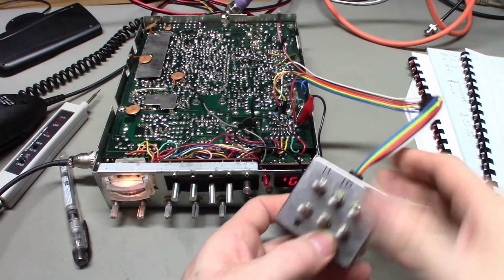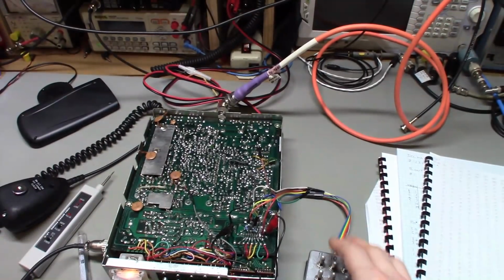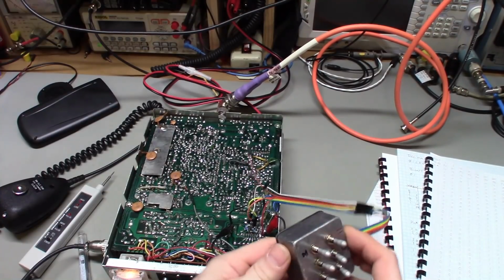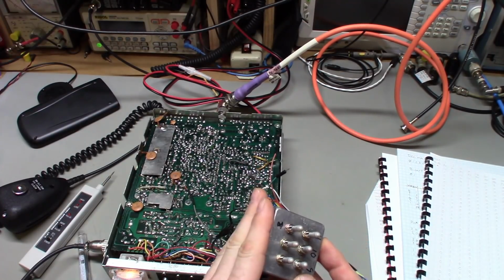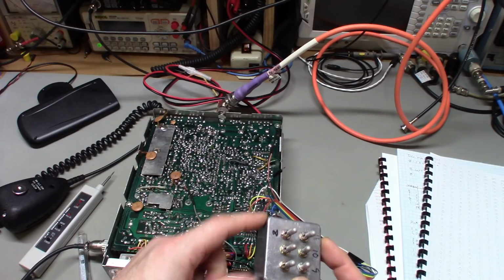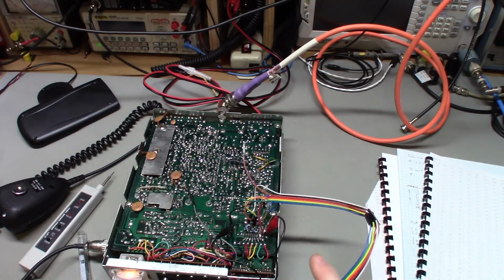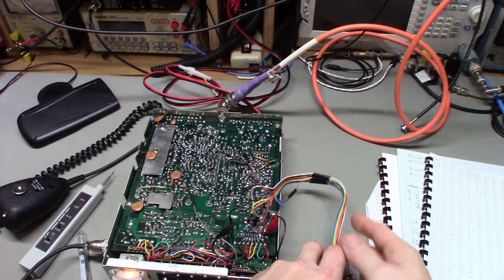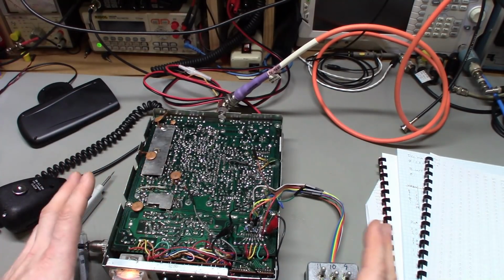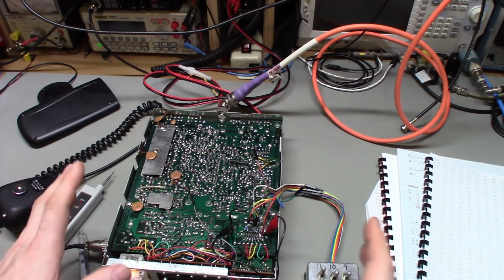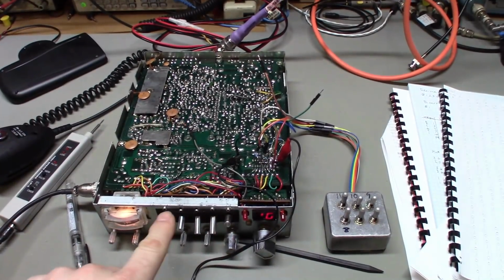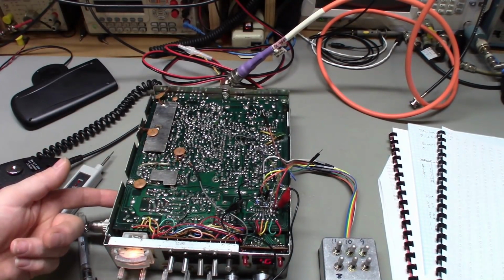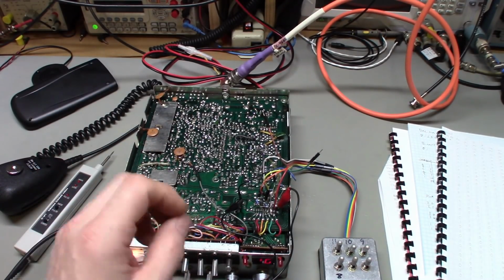If you use ribbon cable, you can make the cable any length you want, so it can reach out to the front of the radio. To mount it, what I usually do is supply the customer with a piece of Velcro tape. That way they can stick it on the top or the side or the bottom of the radio, wherever they want the box. That makes for what I call a no holes drilled installation. You don't have to rewire any switches, and you don't have to drill any holes in the covers or in the side of the radio or in the faceplate to add the toggle switches.